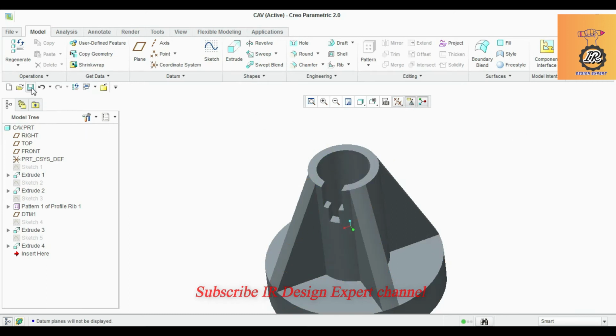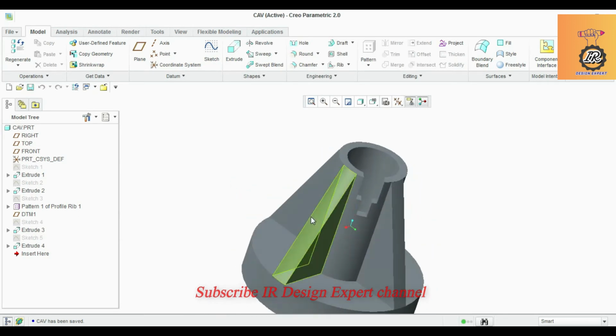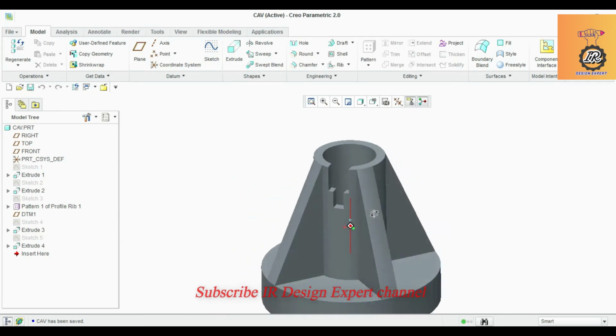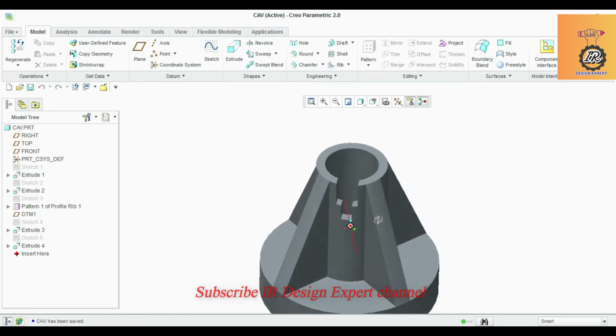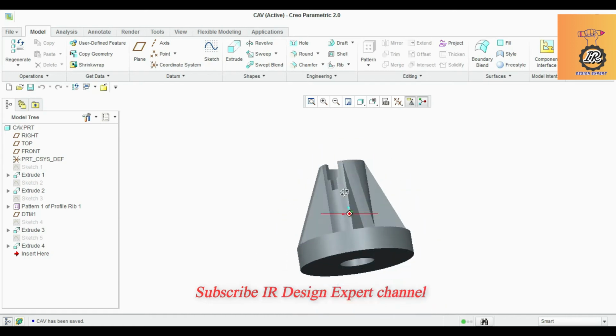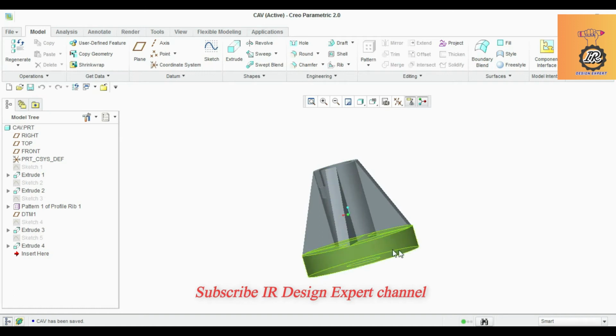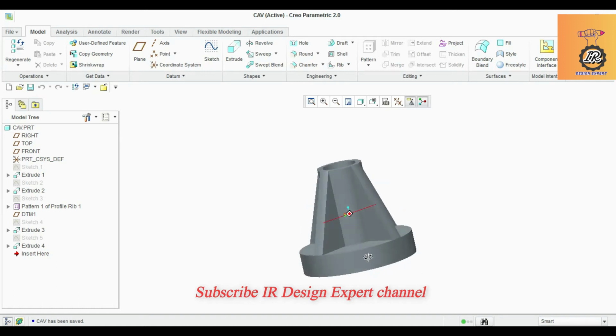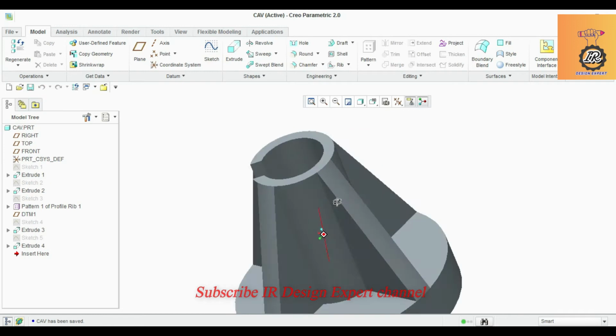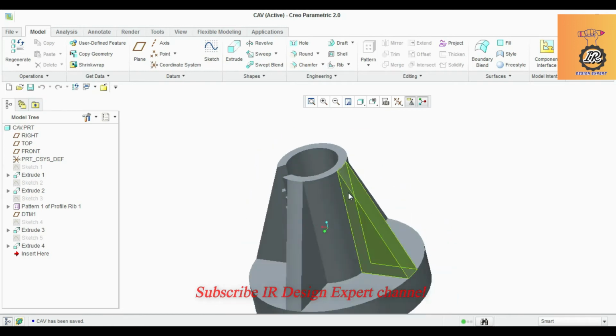So component is ready. Now going to save. Cavity is saved, and then now we can give draft angles. The angles should be given. Before that, this thickness is too high, and the remaining distance thickness are very minimum. So no problem, you can give a draft.